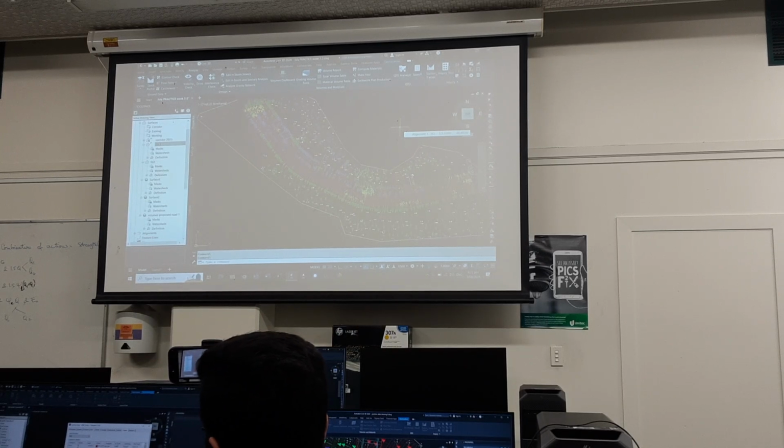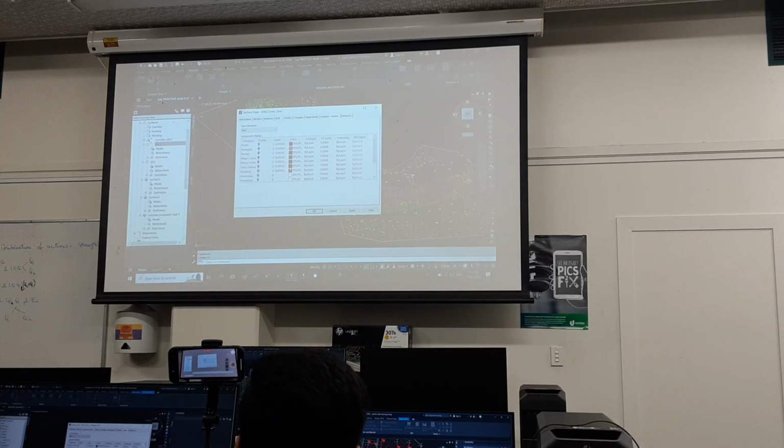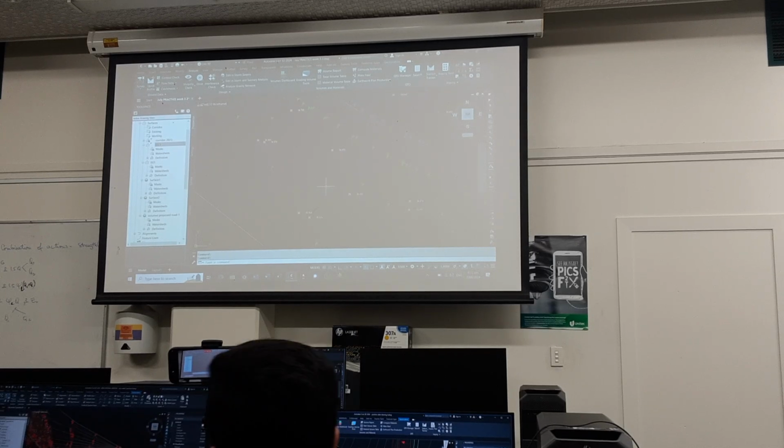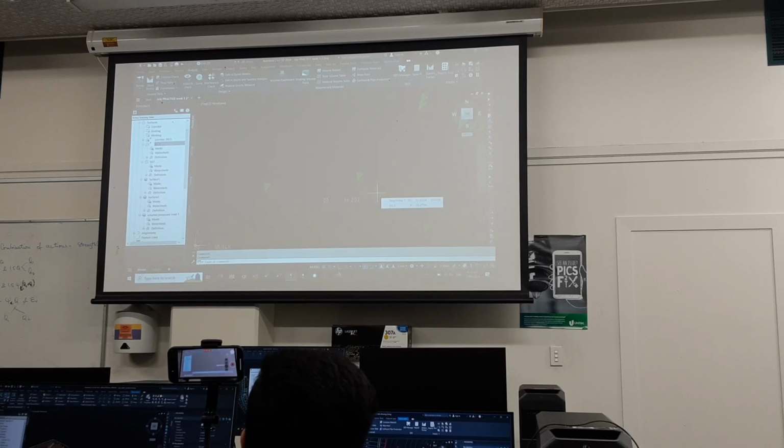So what you need to do, sorry I had the wrong surface there, is right click and go edit surface styles, and under summary, I'd start looking for a slope arrow size that was a bit more fitting. So we'll go to 1 and we'll see what that does. Apply and OK. And you'll notice immediately that the arrow is starting to match something close to the text size. See that?